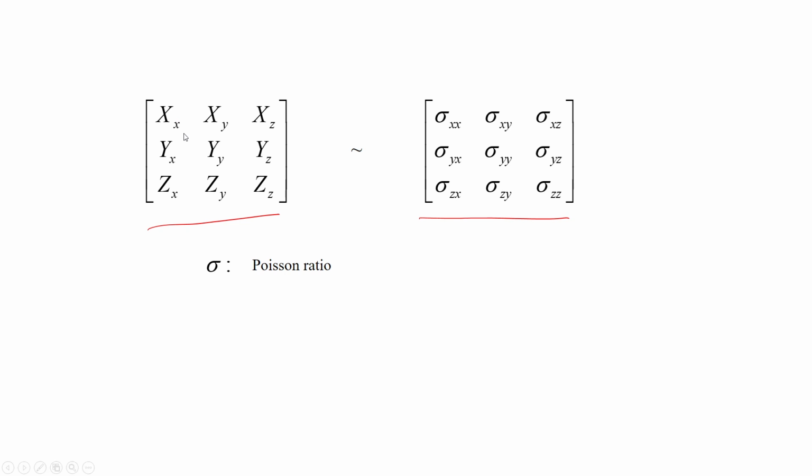So, sigma x x means the stress that acts along the x direction on a plane that is perpendicular to the x axis, which is equivalent. So, these can be used interchangeably. Some books use capital X this kind of notation, some books use this notation, and in my course I may have changed these notations interchangeably, but please do not get confused, this is the same thing actually.